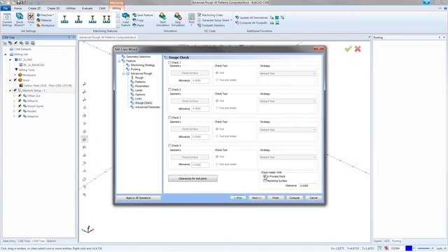In-process stock allows me to move the tool and kind of account for the tool. Even if it was a shorter tool and can't really reach into the bottom, it's going to cut as much as it can and then move inside the area it cut and cut as much as it can inside that area. So it's going to kind of make some clearance for the holder to get into the part, and then it'll continue cutting, but it's all doing that while it's calculating the toolpath.